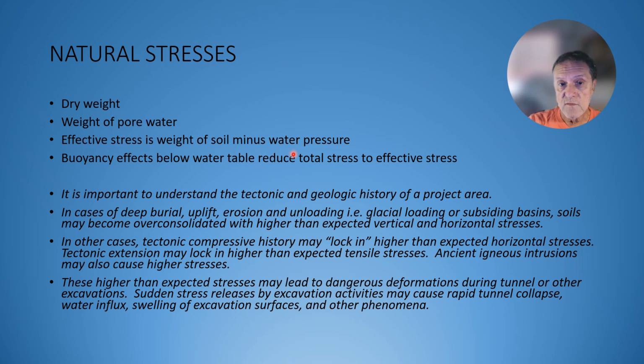Effective stress, and this is a very important principle in soil mechanics, is the weight of the soil minus water pressure. Why minus water pressure? Well, the presence of water in soil pores tends to give earth materials a buoyant force effect that tends to separate grains and reduces total stress. So effective stress is a lower number than the stress you would achieve under drier conditions. Buoyancy effects below water table.